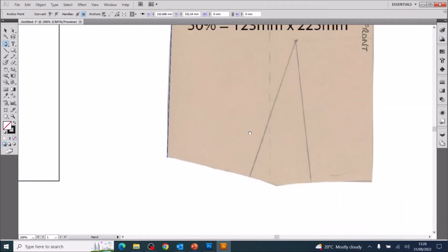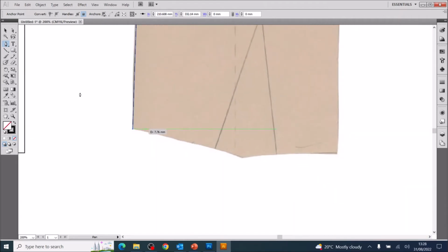I'm going to move with the space bar. I'm still in the tool. Now this has a slight curve, so I'm going to click and drag out a handle to create a slight curve. Hold the Shift key and click back on the end point, and that gets rid of the other handle so that I can then draw a curve from there. Click and drag.